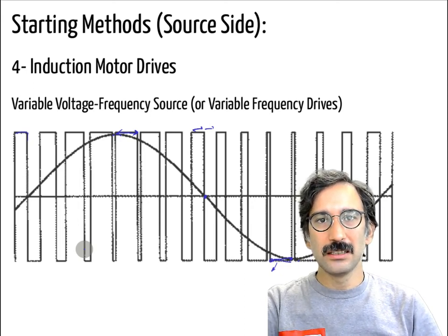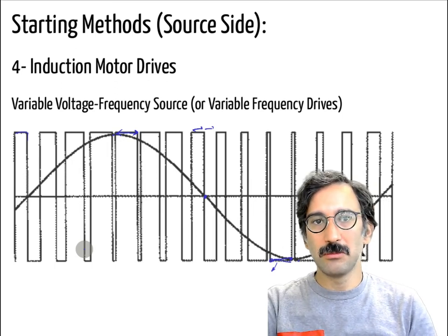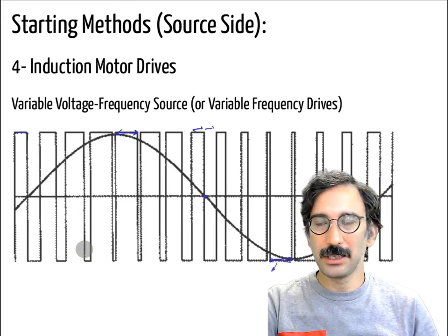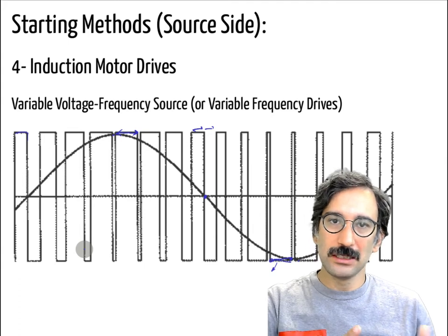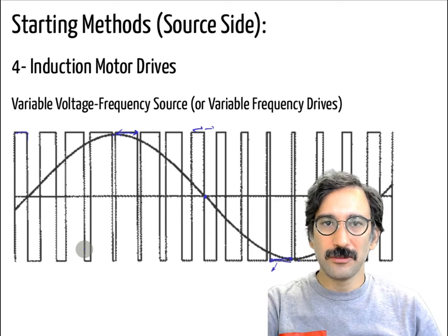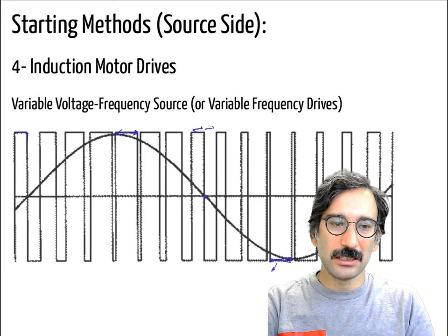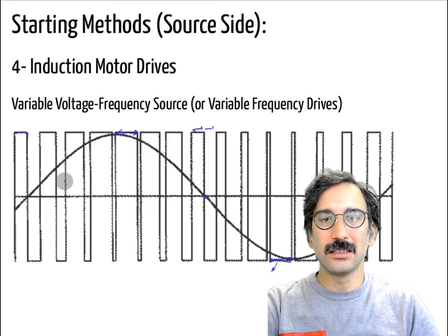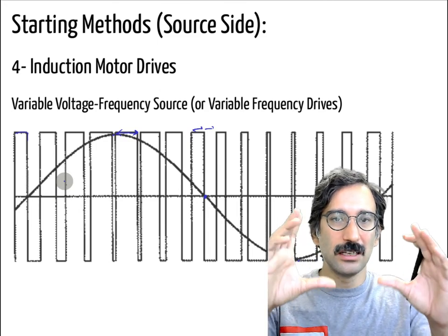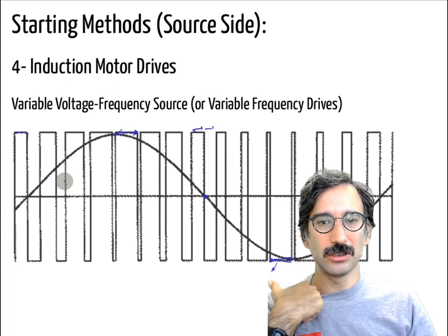Anyway, technically you apply that high frequency PWM signal, like variable duty cycle square waves. But if you take the first harmonic of that, and motors are mostly inductive loads, they are like j omega L, so the RL load is like a low pass filter, and the motor itself filters out those high frequency components. So you end up with a maybe not perfect but near perfect sinusoidal waveform. And by changing the duty cycles, the magnitudes, you can apply whatever voltage you require.